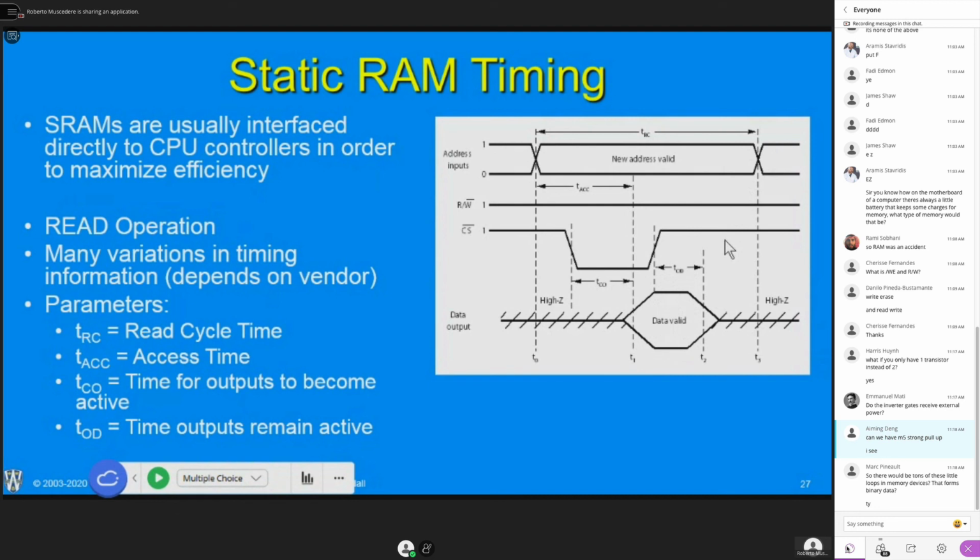That, for example. So again, this is by no means drawn to scale. It's just to try to give you that idea. So the access time is usually the amount of time it takes from when I change the inputs to when the data is valid. But if I change the CS signal, if I raise it at some point, I can always leave it down and the data would be valid for the most part, probably up to here. But if I were to alter it, you can see that there's a certain amount of time from when I change it to the time that it actually disappears. So again, this stuff isn't instantaneous. It takes some time.